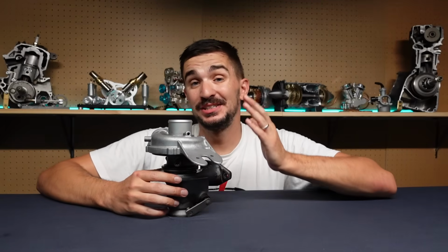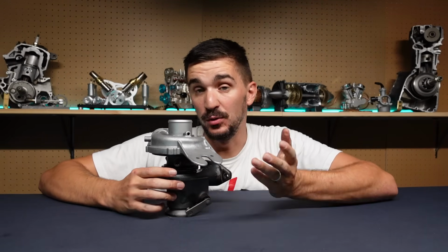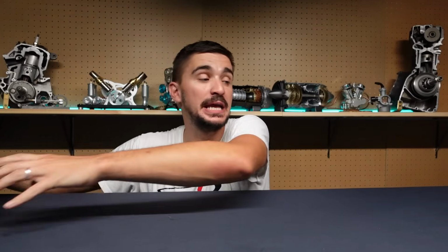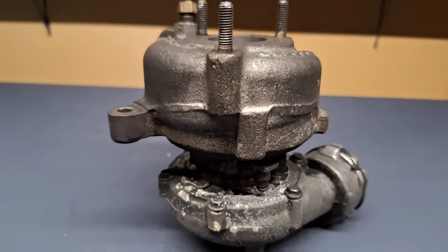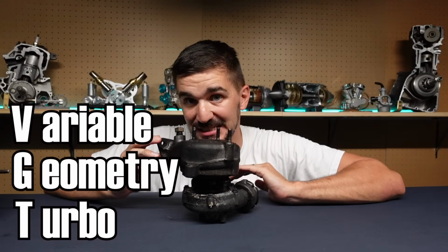Now, a turbocharger does not necessarily need to have some sort of trapdoor, aka a wastegate, to control boost. There is a different way of controlling boost, and it is called VGT or VNT, and that stands for variable geometry turbo or variable nozzle turbo.